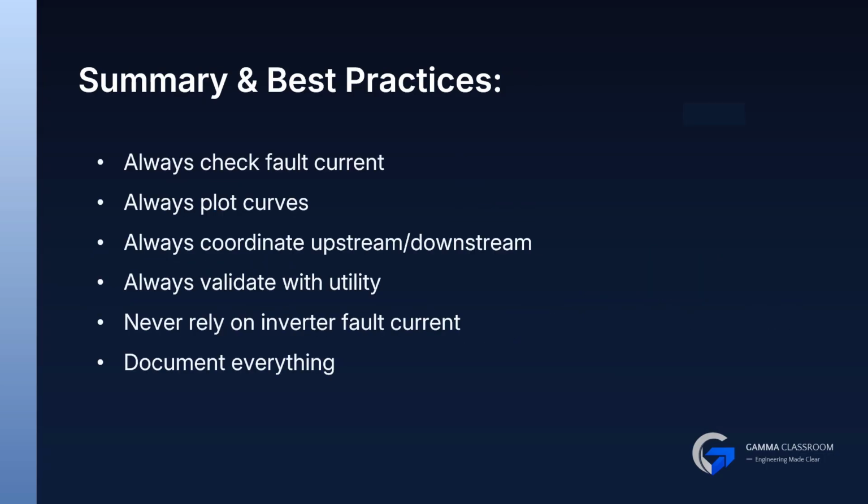To summarize, always check the fault current. Always plot curves. Always coordinate upstream and downstream devices. And always validate with the utility. Never rely on inverter fault current. And document everything. Protection engineering must be traceable.